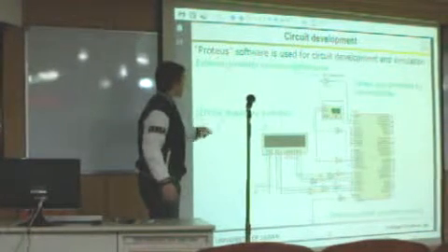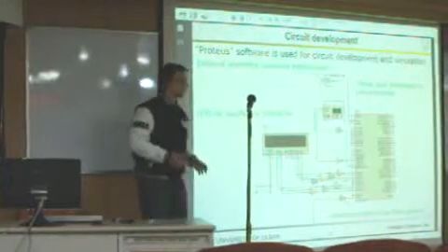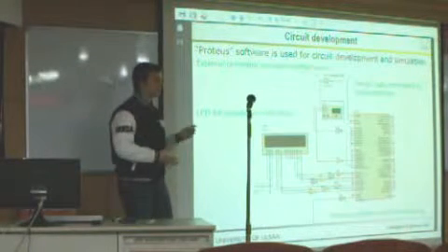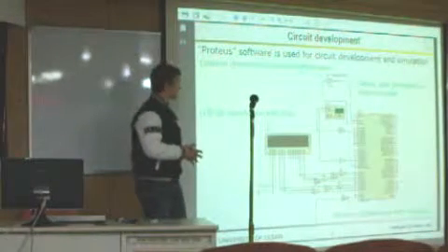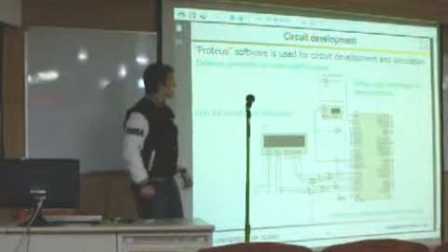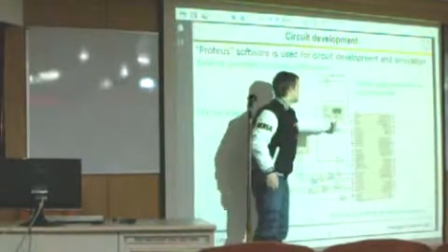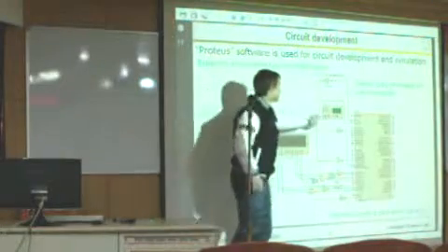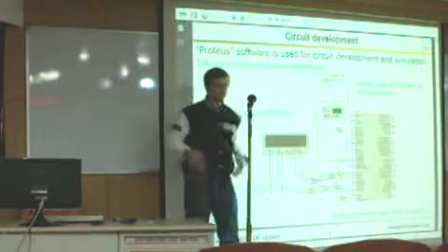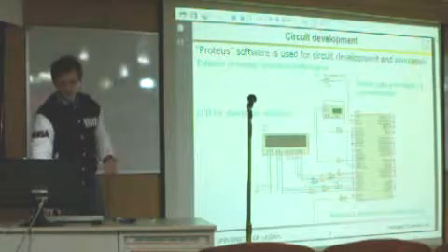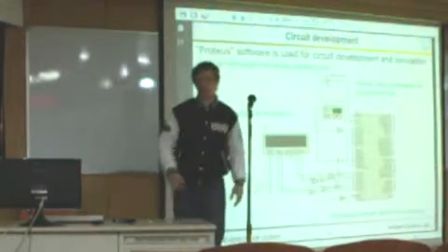And I'm using an LCD for standalone indication of temperature and humidity, and in the future we can show more information on this LCD. And compared to 7-segment displays, this LCD needs only 1 port for function, but if you use 7 segments, you need more ports. And all the sensor data is processed by the microcontroller, and this is my sensor in the software. I can change temperature, and I can upload a real program, real firmware, to this microcontroller and simulate how it works. And after I made all the simulations, I added resistors to each pin to prevent burning of pins of the microcontroller.